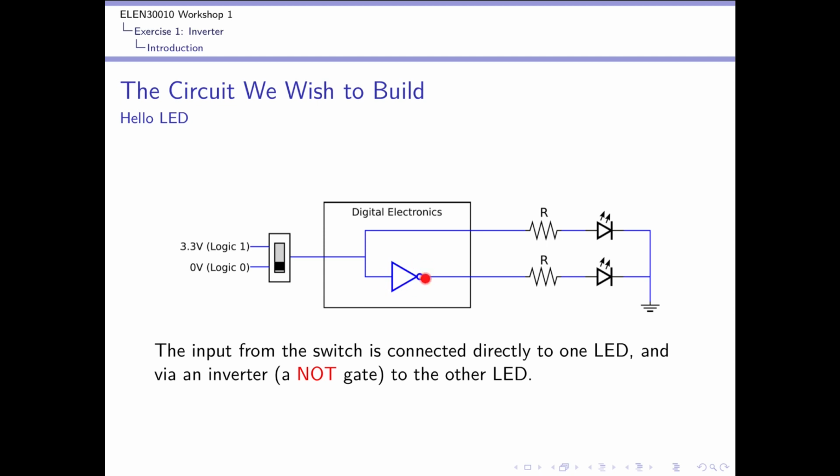It's actually very simple. You only need 2 FETs to build this. If the voltage coming in here is 0 volts, then the voltage coming out here will be 3.3 volts. Of course, there are supply rails not shown here. This guy has to have some power to be able to be an inverter. And conversely, if 3.3 volts comes in here, we're going to have 0 volts coming out here.